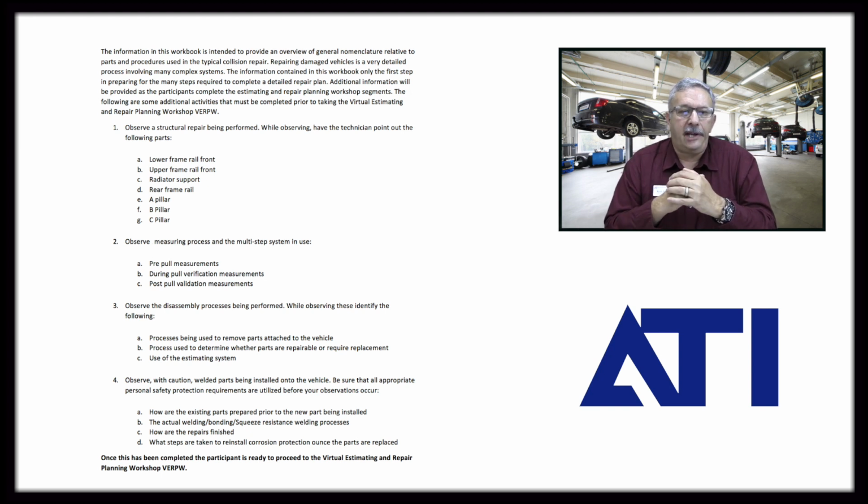Then the fourth one, and this one I'm going to give you some cautions on. We want you to observe some welding processes being completed. However, I want you to make sure that you're protected. If you're right next to it, you're going to wear a welding jacket, at least a leather coat to keep you from getting weld slag onto you, and make sure that you have the appropriate eyewear or a welding helmet so that you don't hurt your eyes. But I want you to actually be able to experience what that technician is doing to install the parts.